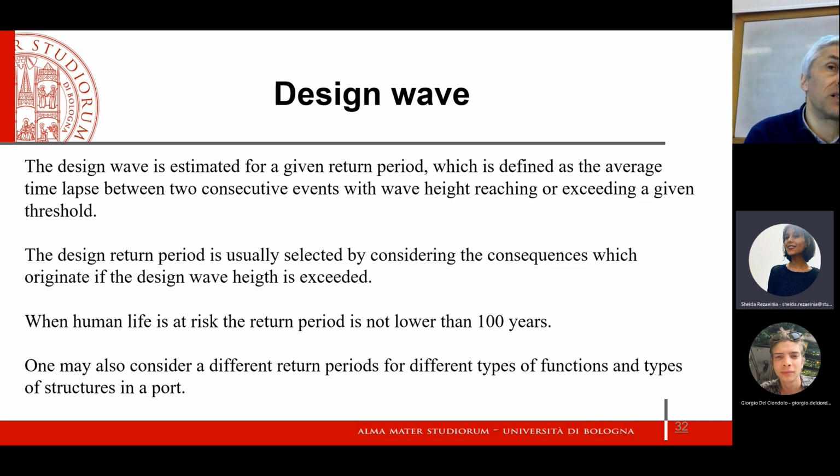So when you talk with the statisticians, they don't know the term return period. They just talk about probability. A return period implies that your data are collected as a function of time, which is perfect in our case because we are talking of waves, wind, observations, so they are recorded at a certain time. Statisticians talk about probability or frequency because their observation may be something like tossing a coin, which is a function of an index, i, toss number 1, toss number 2, but not of time.